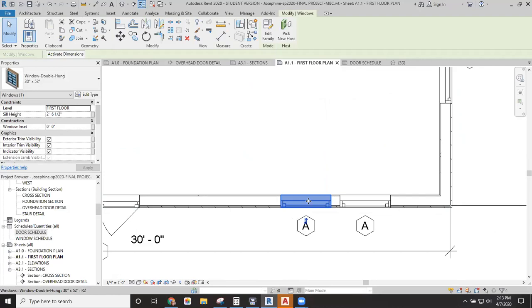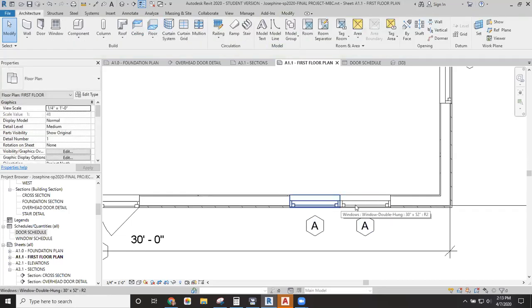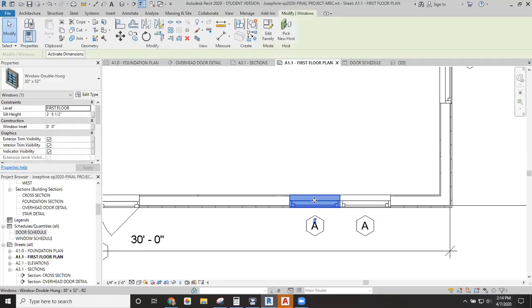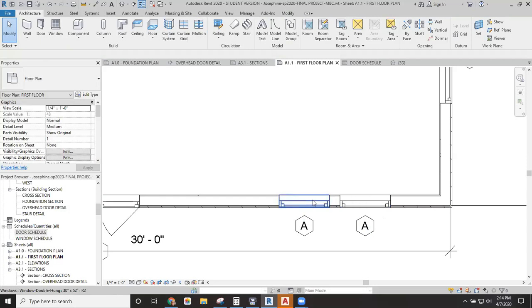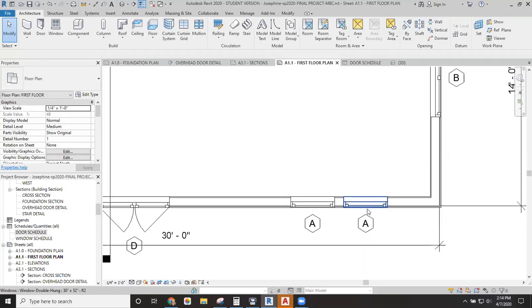If you're doing this in AutoCAD or by hand, and you draw these windows so that there's absolutely no wall in between the windows, it's better to consider that all one big wide opening because you cannot get any framing in between those windows the way you've drawn them. So if you draw the windows so that there's a little bit of wall between them, consider them 2 separate units.